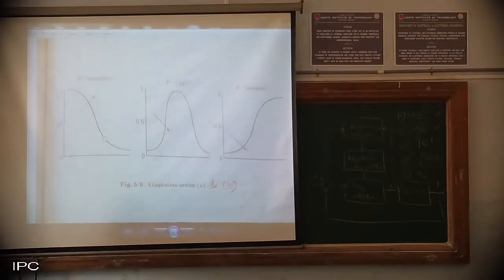Now, how exactly are we going to apply adaptive actions A and B? This is going to modify the membership function. As our title itself says, membership function tuning using performance criteria, so we are going to tune our membership function. The membership function is nothing but a shape. We have considered the error, which is negative or positive.